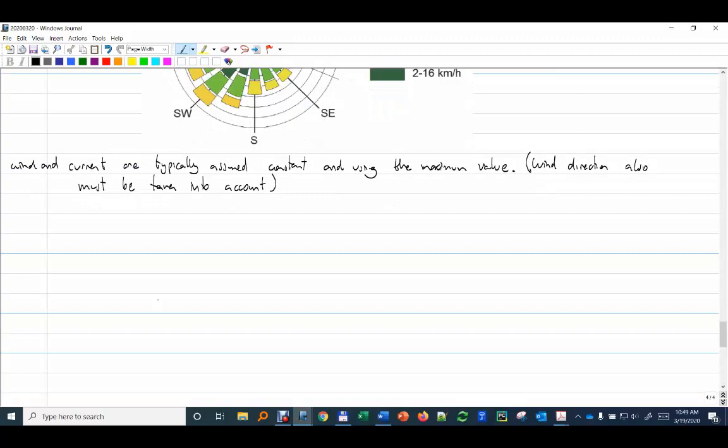But one very critical marine load that people have to look very carefully into is the wave. Waves, like I mentioned to you before, if we talk about the elevation, we use this strange zeta letter, in meters. And elevation is essentially the amplitude.